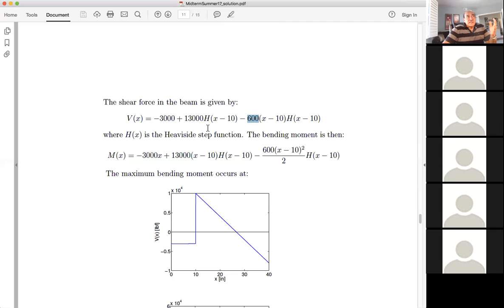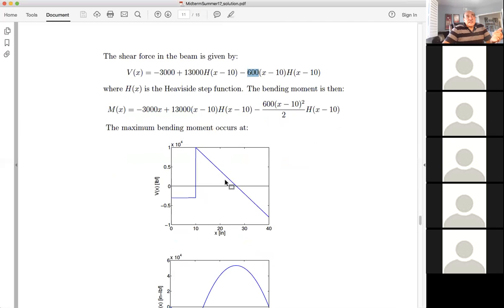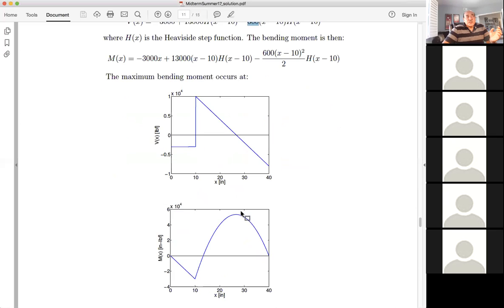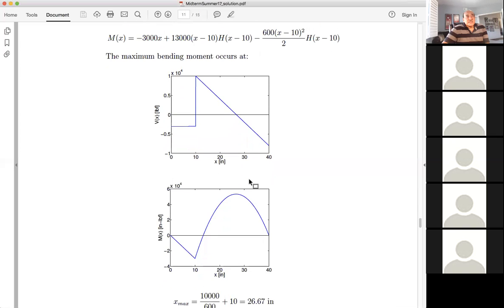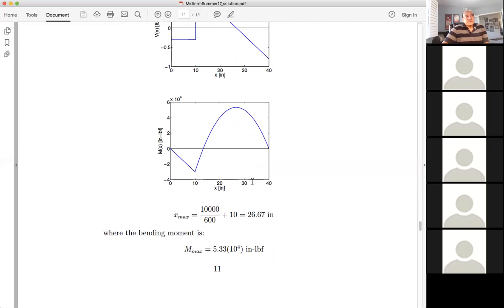So instead of doing the integrations, you just find the value of the moment at that point, by whatever means, by taking moments at that point. So this is the maximum moment that you have. We got that number here, and that number here, and these are the two numbers that actually count to find the required shear stresses and maximum shears.